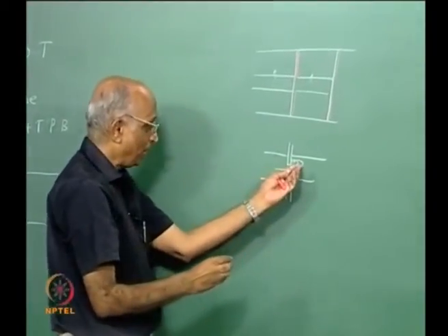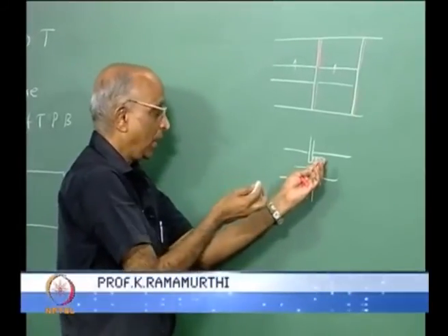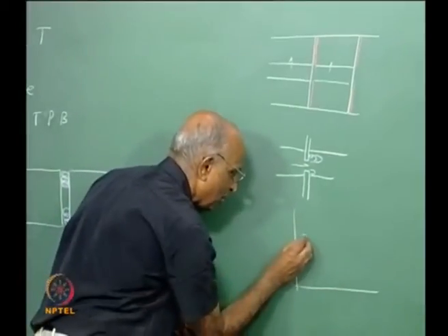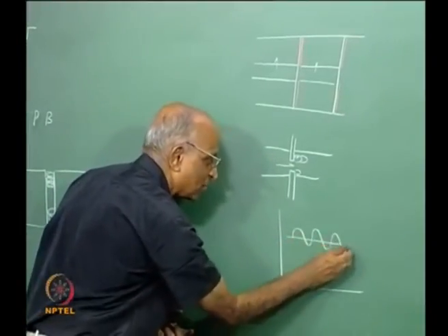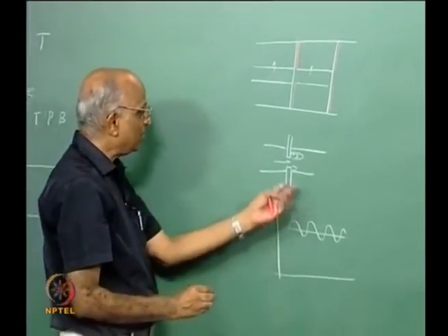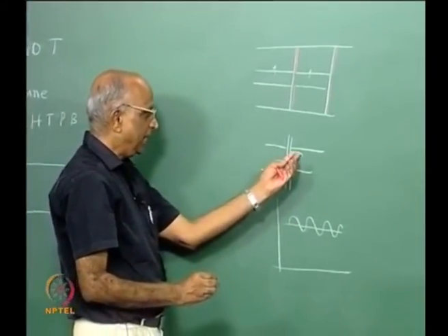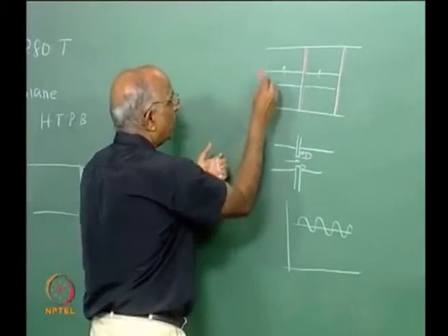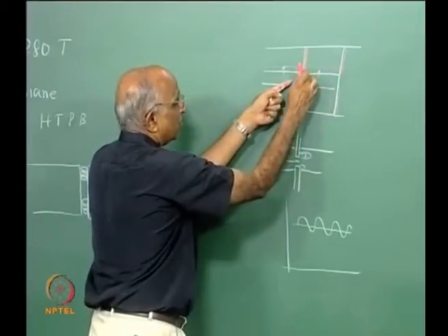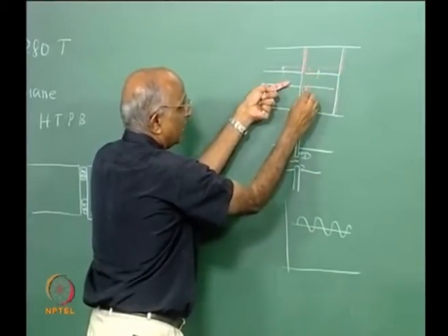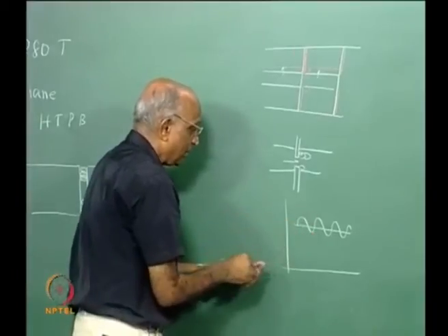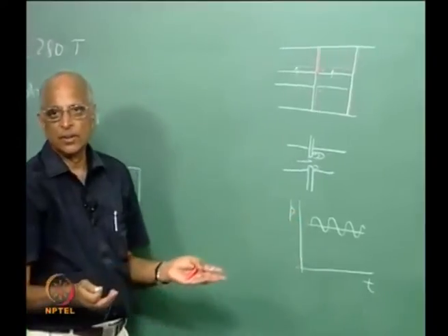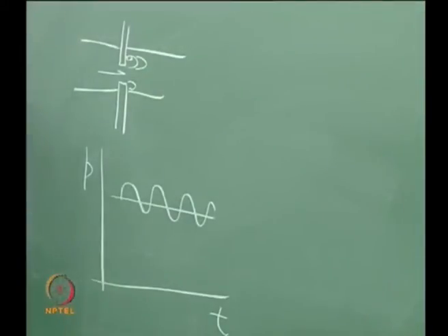These eddies in the flow have a characteristic frequency of disturbances, and these disturbances get amplified, and the thrust, instead of being steady, starts oscillating, and the oscillation is because of the eddies formed, because this fellow projects when the propellant has burnt over here. Well, I have this protrusion standing like this, and this causes the pressure to oscillate. We will see such mechanisms when we look at the chapter on combustion instability.